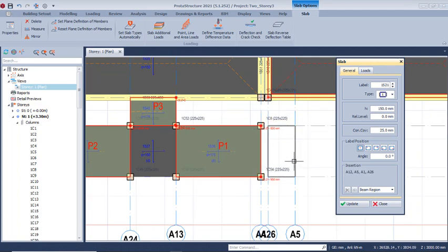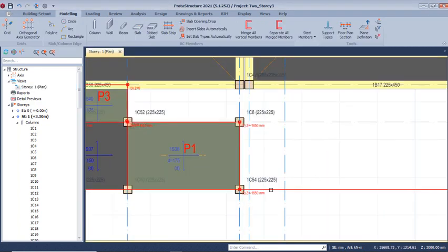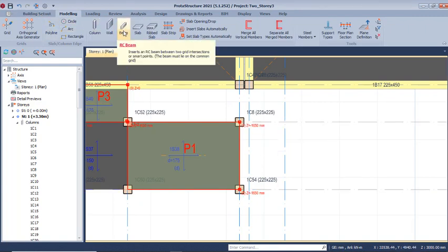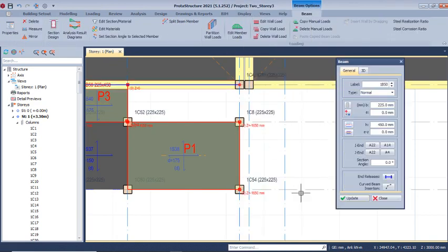We need to have a beam to support this slab, a cantilever beam, so we have to close this at first. At this point here we'll be having a cantilever beam, so we will go to beams, or we select any of these beams, then click on its property. The depth of the beams is supposed to be the depth of the slab, so we wouldn't want the beams we are going to have here to have more depth than the slab.